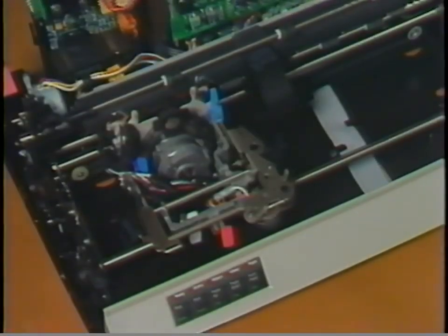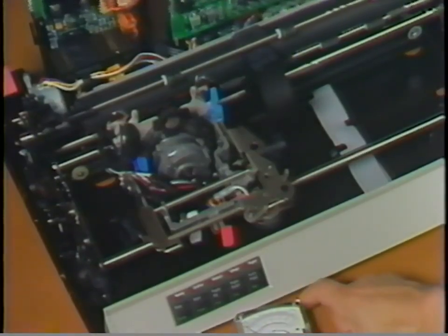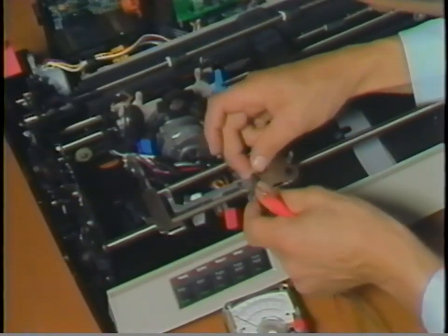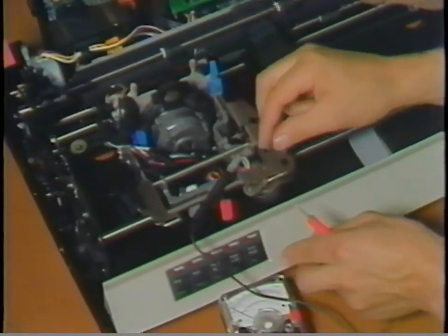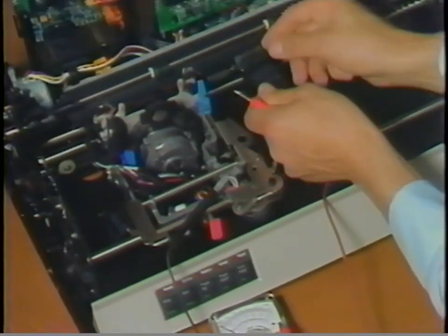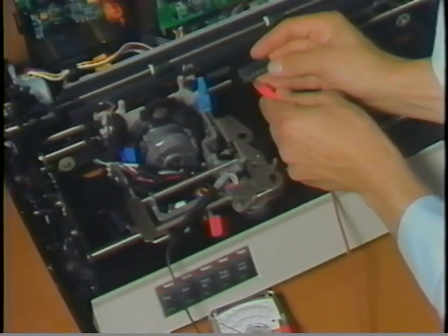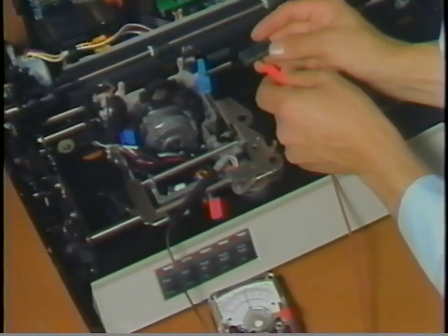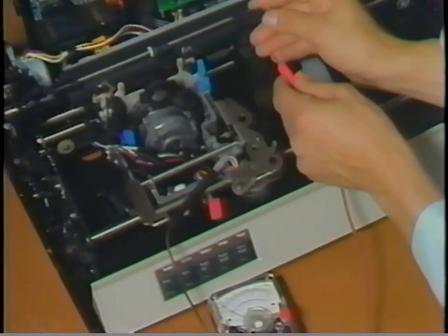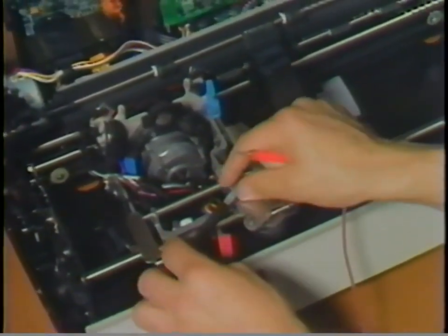In order to perform the ribbon feed motor resistance check, you would plug one of your meter leads in the test connector on the motor and measure the resistance from the test connector to each of the feed motor pins on the lower side of the carrier cable connector. The resistance check for the paper feed motor is performed in the same way as the transport motor resistance check.